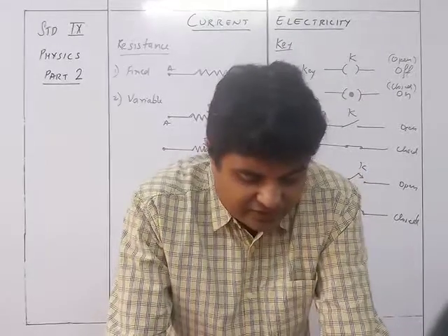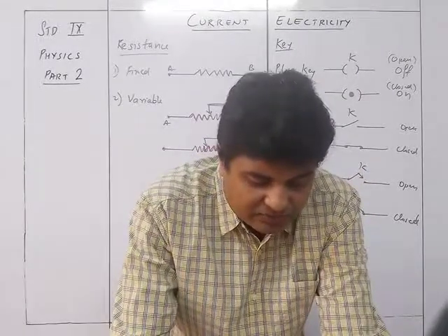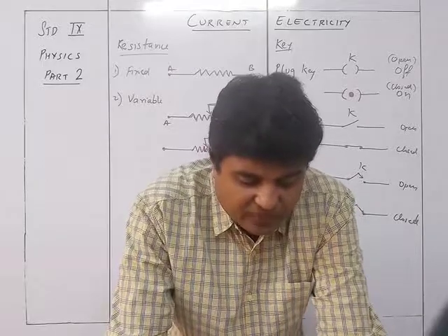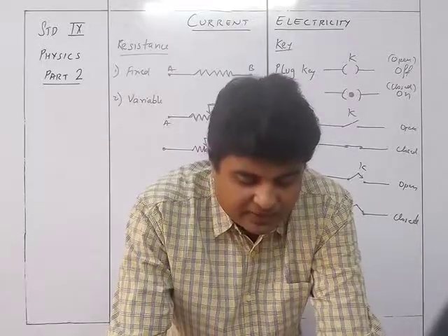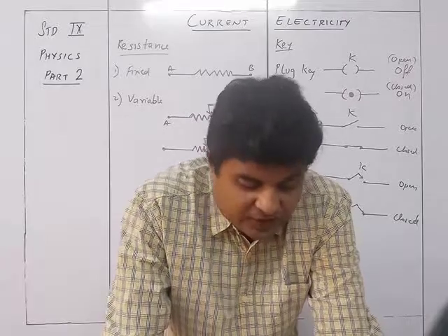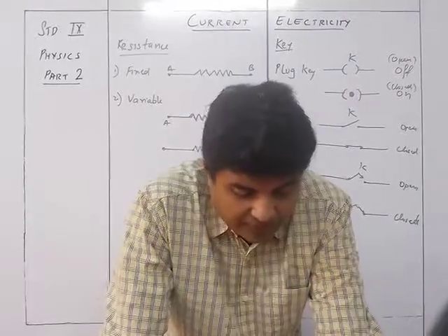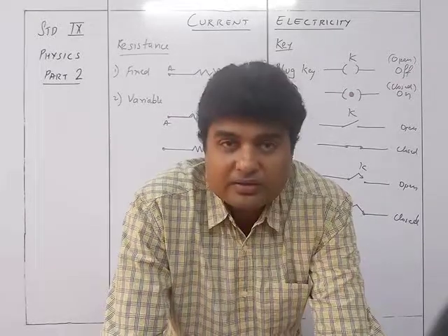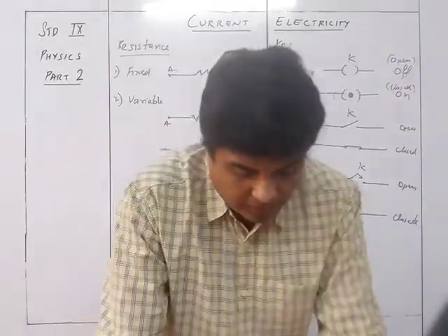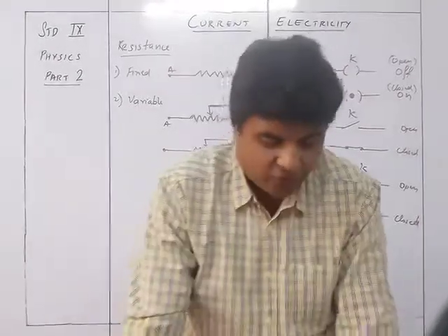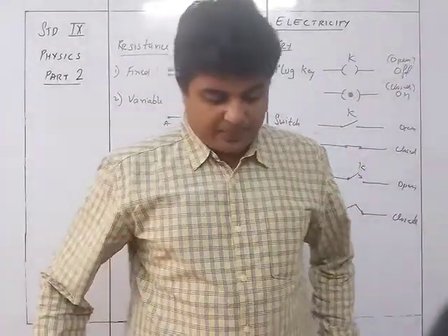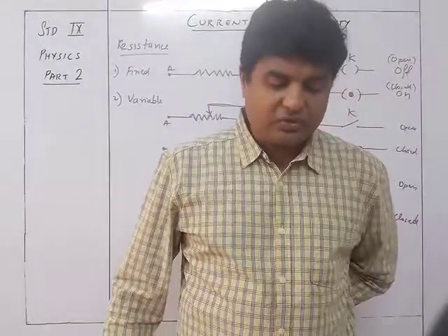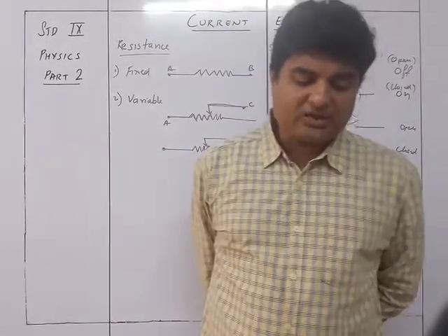A rheostat is a device by which resistance in a circuit can be varied continuously. It is used to adjust the magnitude of the current in a circuit by changing the length of the resistance wire included in the circuit. As shown in figure 9.5, it consists of an enameled constantan wire. Enameled means insulated. The enameled constantan wire is wound in the form of a coil over an asbestos pipe fitted in an iron frame and provided with a sliding contact, the jockey, on the brass rod.